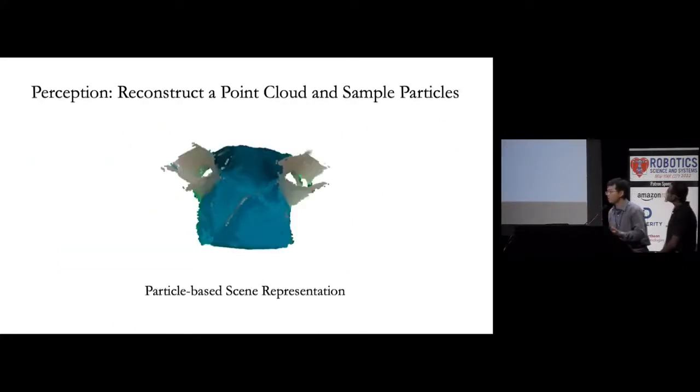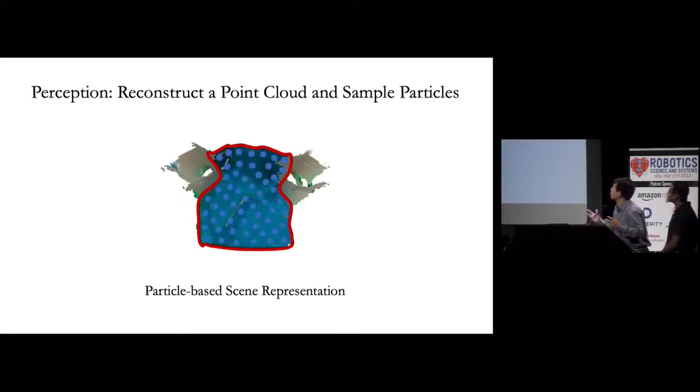In the perception module, we first extract the plastic point cloud from the scene, then reconstruct a watertight mesh around the point cloud, and lastly, sample a sparse point cloud inside the mesh. Then we will have desirable inputs to our graph neural network.